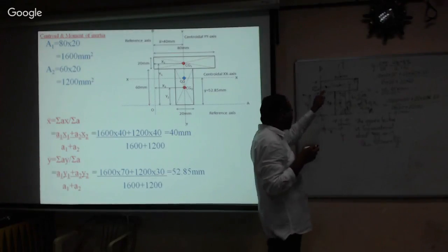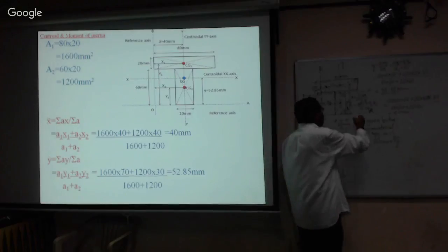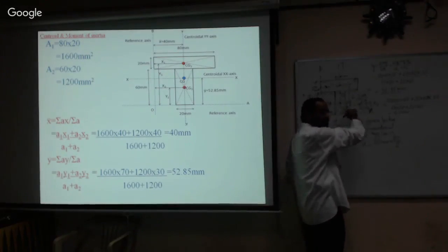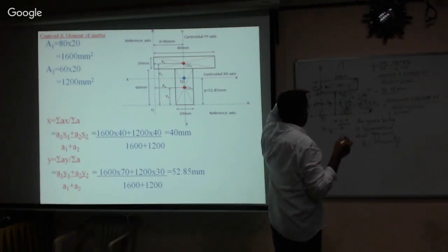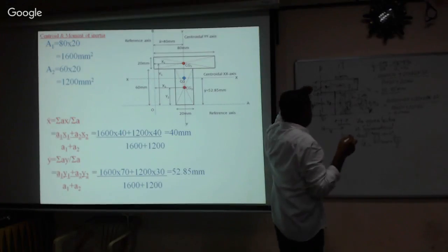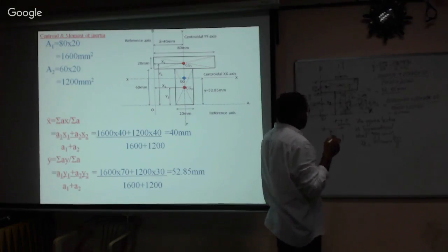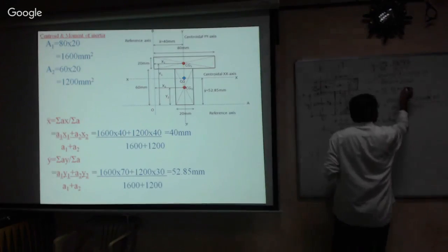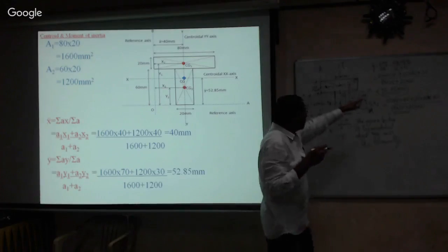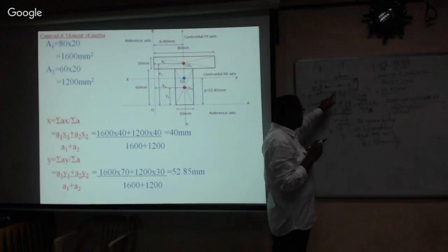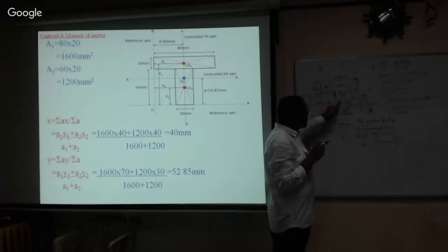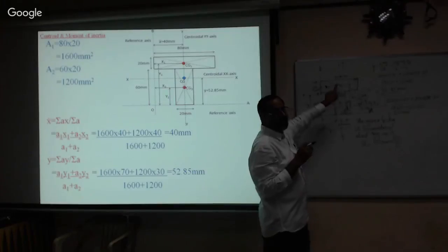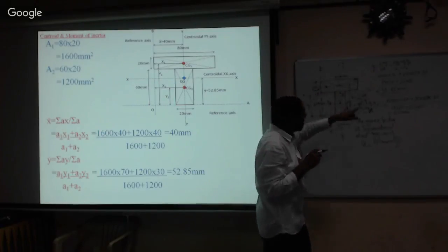Therefore, now you tell me the centroid of this figure. Our assumption is right. It is less than 60, therefore it is below. Alright, now you just check once again. Suppose the answer is wrong here, and the y bar is more than 60, our centroid shifts to this point. If y bar is less than 60, then our assumption is right. Otherwise, you have to change it after your calculation. You just go through once again and find out.